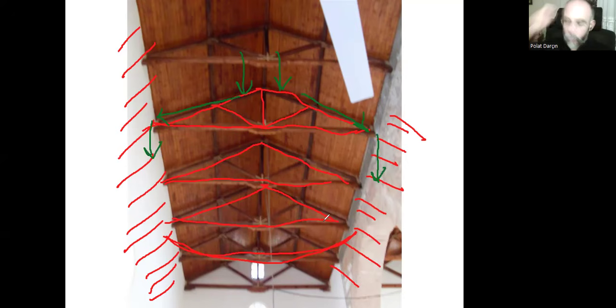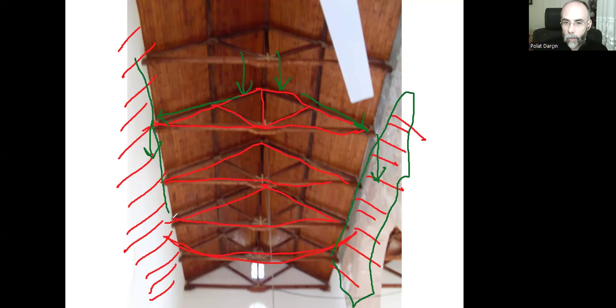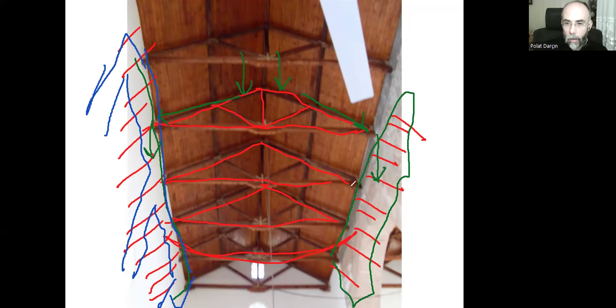In this example, most probably this is a traditional building, some old historical building, and these are masonry, stone masonry walls. All this surface here is a load-bearing masonry wall. Most probably there's another wall here, but instead of masonry walls, here on these ends, we can create reinforced concrete beams and reinforced concrete columns, the usual building structure that we learned last semester.